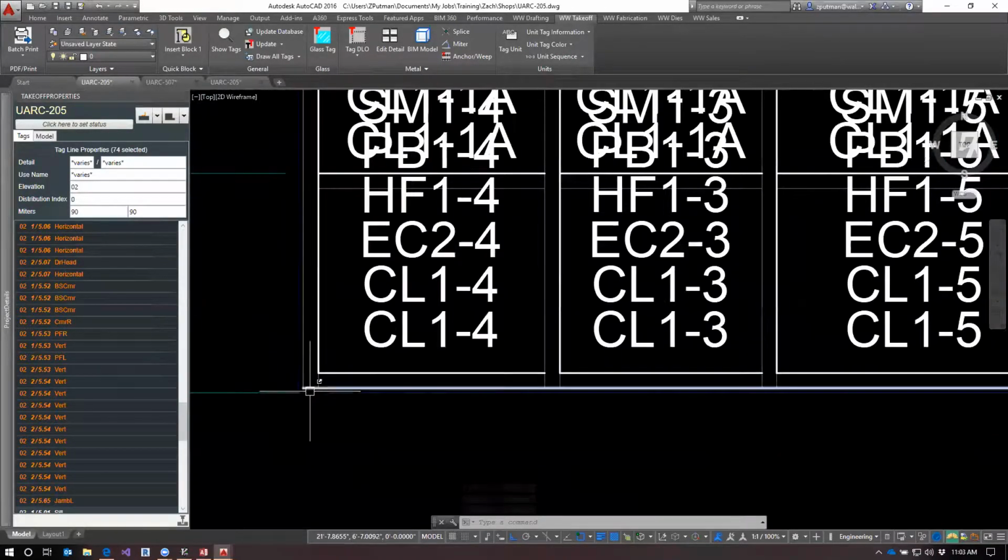What I want is a short tagline here that hits the center of each of these mullions, or maybe it's off to one side, I don't really care, that has a single T-clip on it, or an F-clip of a fixed length. You'll have to rotate that one just like we did for this angle, because the T-clip isn't extruded up and down, it's extruded in and out of this elevation.